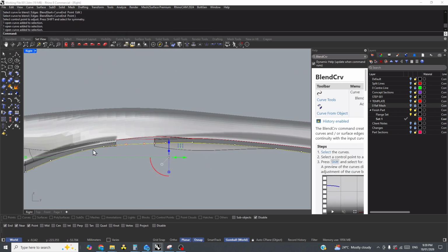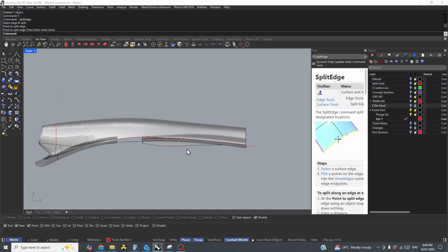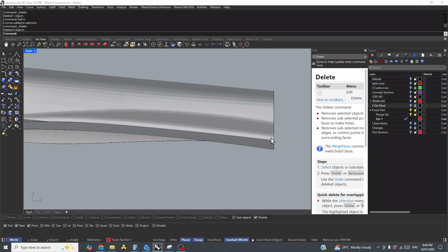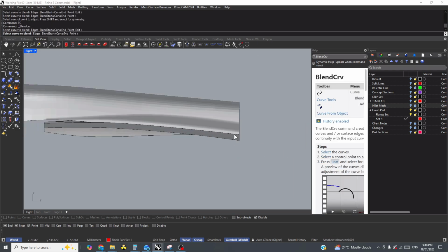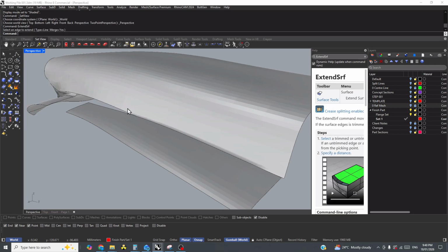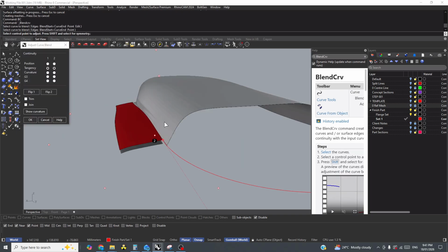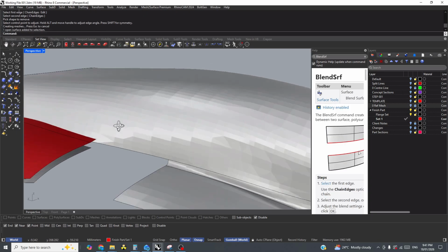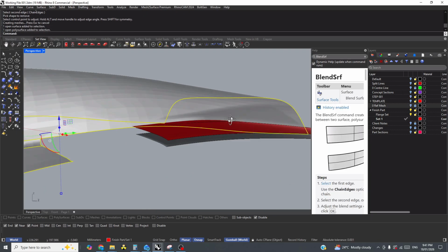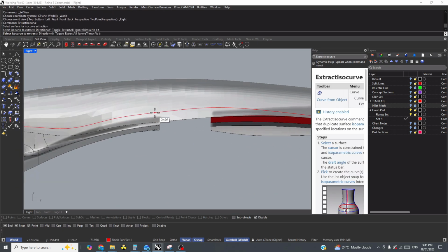That works quite well. It looks like I didn't take it all the way here because we've got a higher spot through the middle there. But under normal circumstances, say you've got your bottom plane, you can offset it, and just like that. And so there we go. So I offset the flanges and created a blend surface between them, then use that as an intersection plane. That's a good idea.